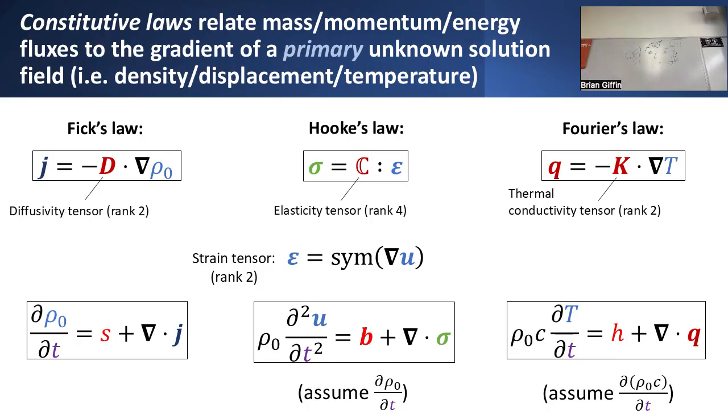Similarly, I might want to describe stresses in terms of something that has to do with the deformation or the motion of material points local to some chunk of material. Or in other words, strain. I want to come up with some relationship between stress and some deformation quantity, i.e. strain, that gives me a connection back to these fundamental or primary variables of interest.